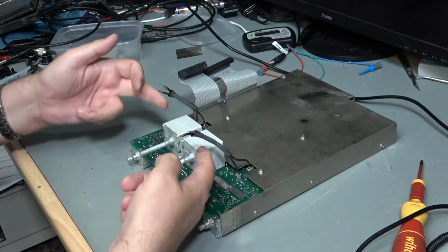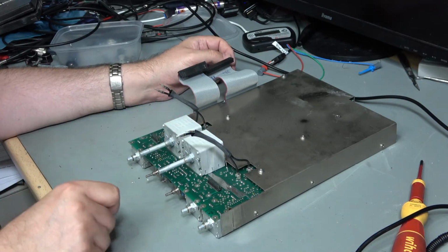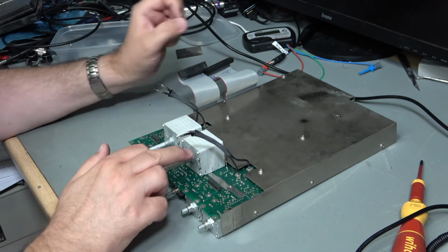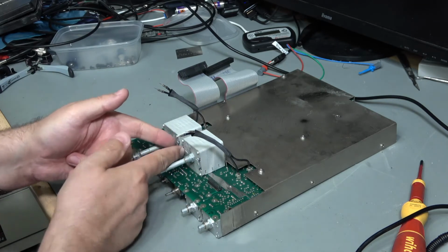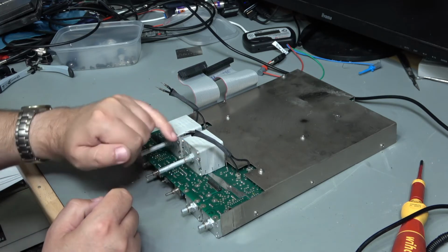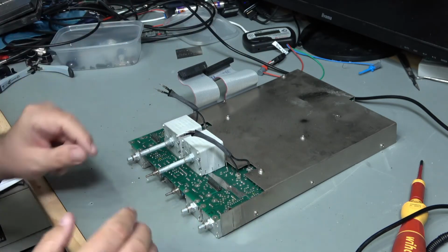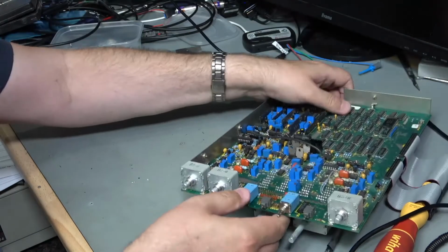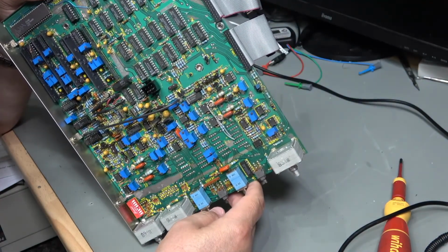So I've seen a few people commenting about these switches here, these multi-layer switches, which are also custom built with stackable wafers, about the difficulty of cleaning them. I'm not sure that necessarily is the case, because these come apart by crimping these two. You have to twist these metal lugs so that it'll slide off, and then you crimp these little, they're almost like plastic rivets, and that should withdraw then and enable all the wafers to fall apart. But of course you've got to do that carefully, because otherwise things are a mess. But fortunately I think we're okay, we don't need to clean those. Could do as a matter of course, but yeah, let's leave alone what isn't broken, I think.